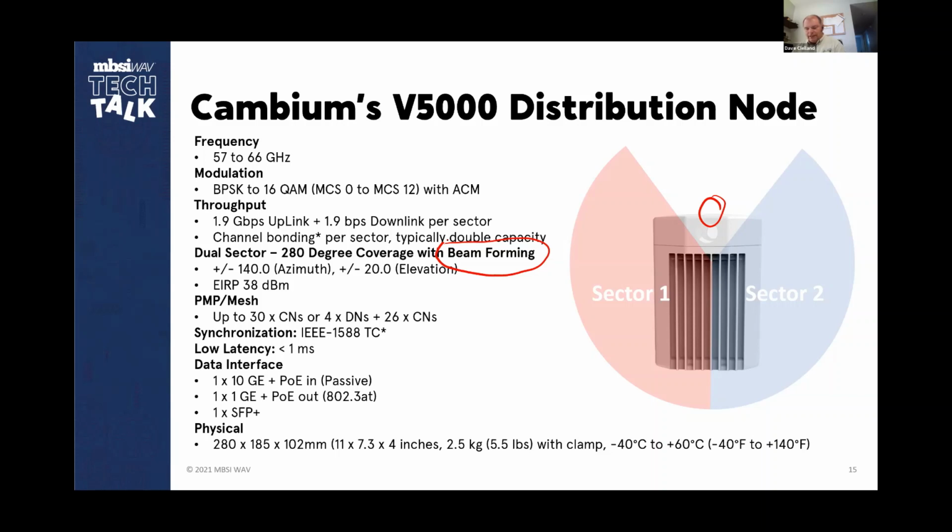Again, when we use the high gain, we're talking about 1 degree or less than 1 degree of beamwidth for the subscriber unit. So we have to be quite accurate about this. But the short range means that we have to be able to see the distribution node. It's going to be a little bit tricky for the first few installs that you do of this kind of equipment. Once you get used to the sensitivity of the azimuths, it's going to become easier and easier for you.